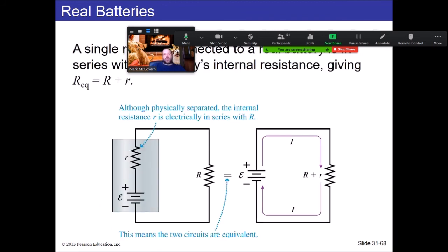If you're going to solve a circuit like this, you basically consider the fact that your internal resistance is in series with, say, another resistance. Like in this example here, our internal resistance is going to be in series with a regular load. So it's almost like the load has a higher resistance, so we just treat that as R plus R. And then we can figure out our... You may have a problem with that, at least on either this homework or the next homework.